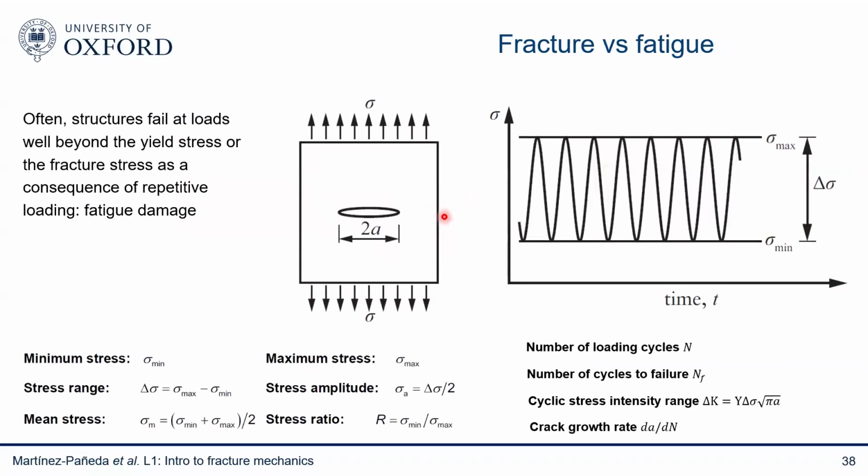So one of these sources of degradation is, of course, fatigue. Most engineering components are subjected to cyclic loading, and I would say 90% of failures today are related to either environmental or fatigue factors. What happens is that, of course, you're applying a load that is supposed to be safe, but because you apply that load millions and millions of times, you are actually doing small degradation of your material, and you actually damage your material. It's not enough to grow a crack, but eventually, after applying a lot of load, the crack does indeed grow.